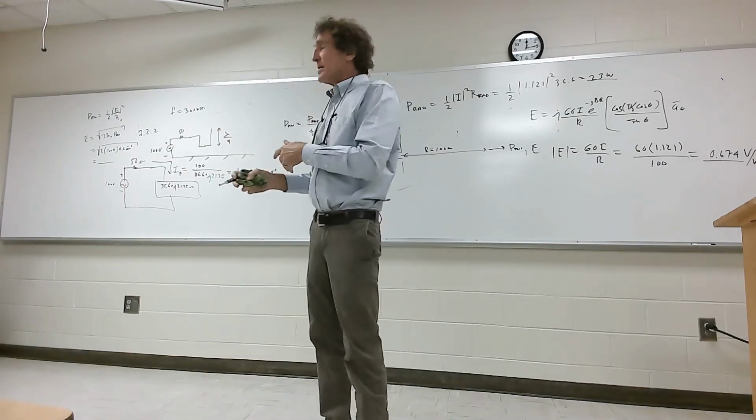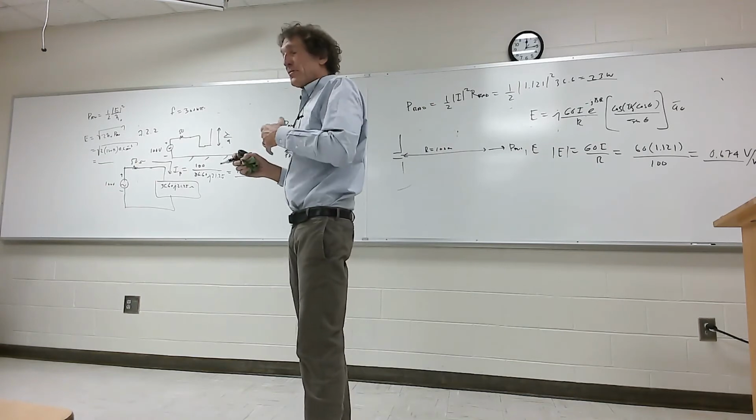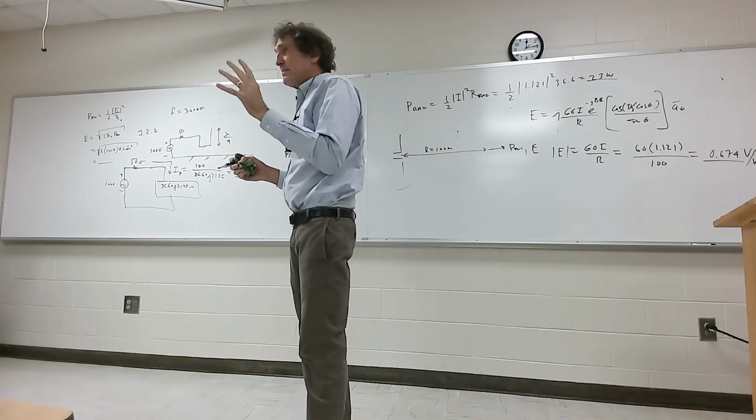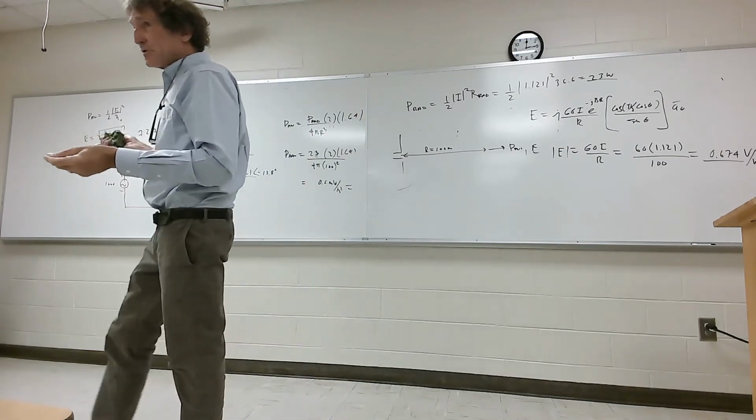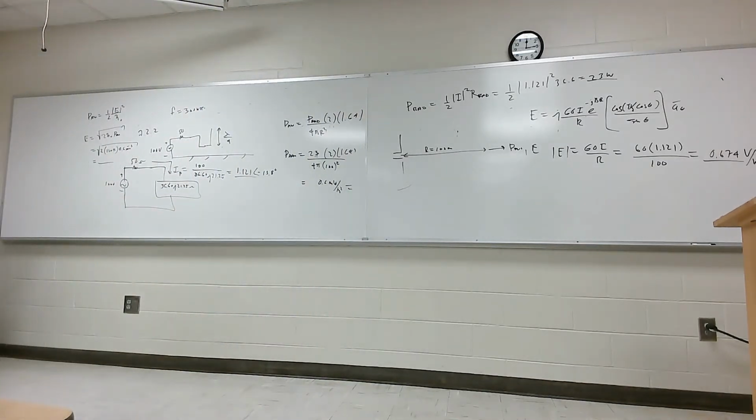Now, I usually use the total power radiated by 4 pi r squared times the gain, or directivity, to get the power density, then I derive the E field or H field. Usually that's quicker. For this one, you can go either way. If you want the E field, you can get that. And by the way, if you took that E field and went back and got the power density, it'd be the same. But that covers all bases of that question, right?